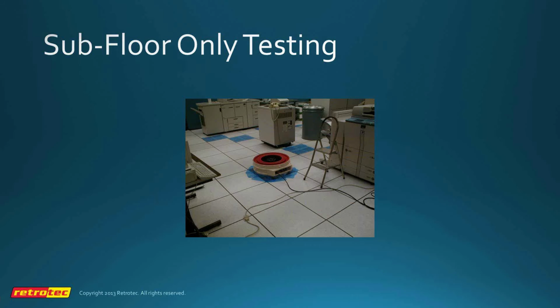So what we do to neutralize the flow across the floor is we pressurize the entire room. Here we have a fan in the floor that's measuring the subfloor only leaks, and a fan in the room will be pressurizing the room to get the pressure across this, I call this the walk-down floor, to zero. The fan that's pressurizing the room will set it to zero between the room and the subfloor only. And this one is measuring the flow that's required to pressurize the subfloor to either 10 or 50 pascals.